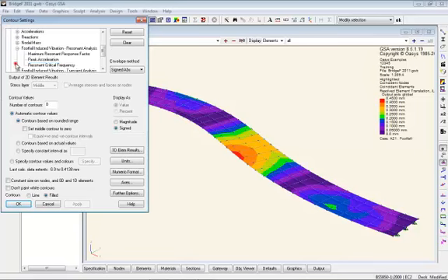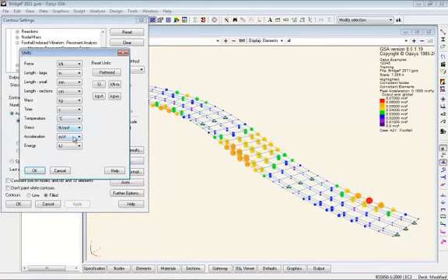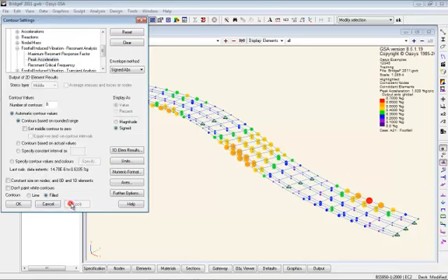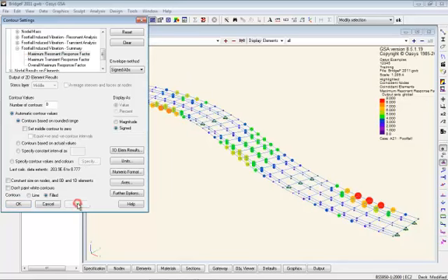So initially you get nodal results such as accelerations there, which I'll just change the units to %G, which is the American preference, 0.7% G on there, or you can get velocities out of here, or the overall response factor, such as we're looking at 9 for resident, transient not a problem, 3.5. The overall worst of both cases.